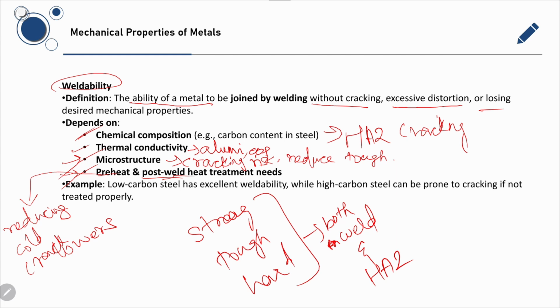It tempers the heat affected zone and weld, and it reduces the residual stress and can recover the toughness. Here, post-weld heat treatment recovers the toughness.